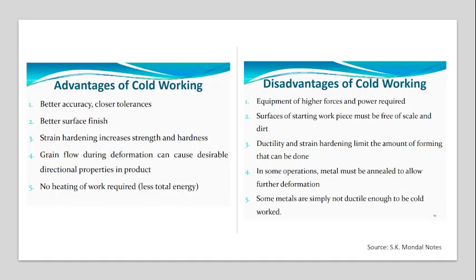So what are the advantages of cold working? It will give you better surface finish, better accuracy, and strain hardening. See, strain hardening will be there in cold working, so it will increase the strength and hardness. And then no heating of the work is required.